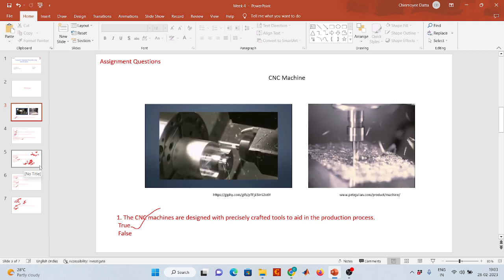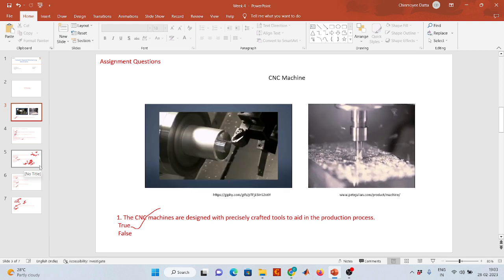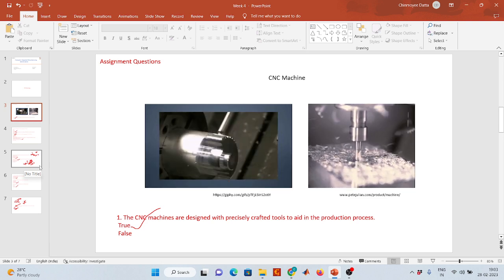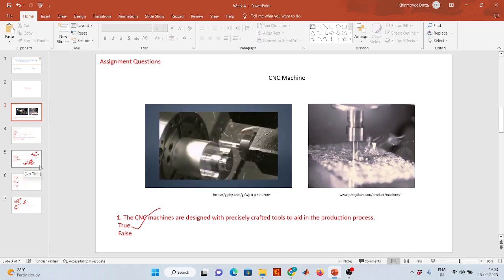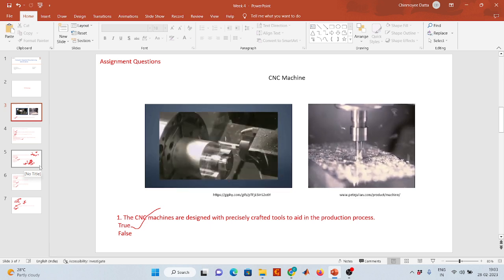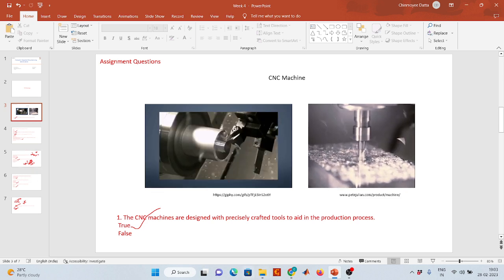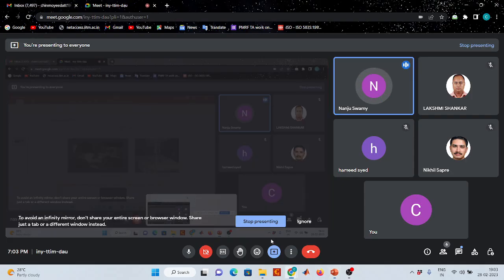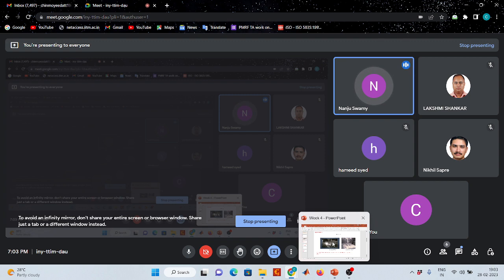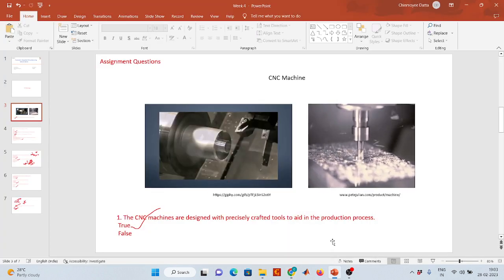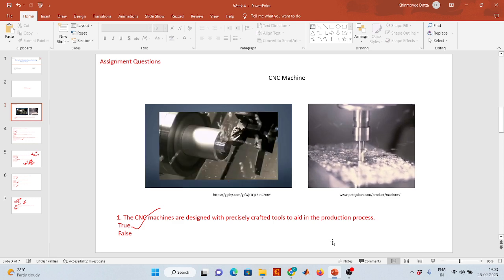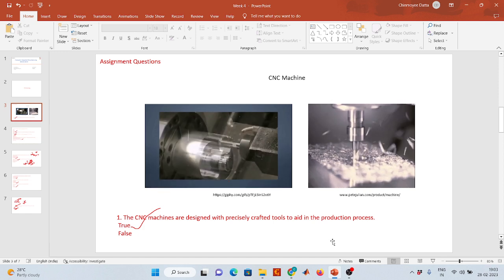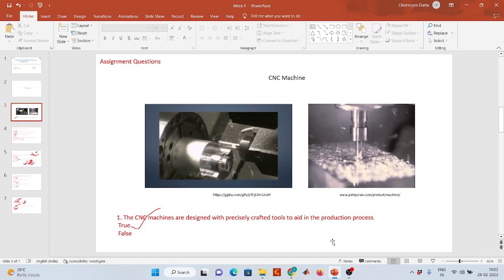Only the coloring will happen sometimes when you do the welding. Basically, I see the coloring only when you do the welding. Machining, we don't get the color. If the color happens, then we may have to reject the component. So generally, flood coolant is used in titanium machining.